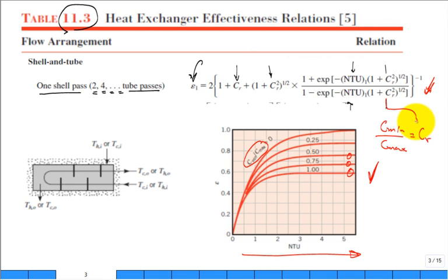So what we do is we say, well, what was our value of the number of transfer units? Around 2.24, right? Where is that on the x-axis? Here's 2.5. Here is half, 2.24. Right? Okay, and then for our C sub R, it was 0.027. Well, it's either 0, or 0.25, 0.5, 0.75, or 1. Let's call it right there, a skosh below the red line.